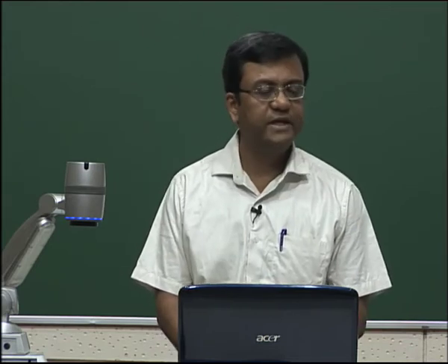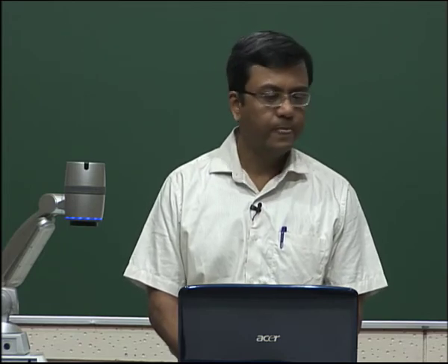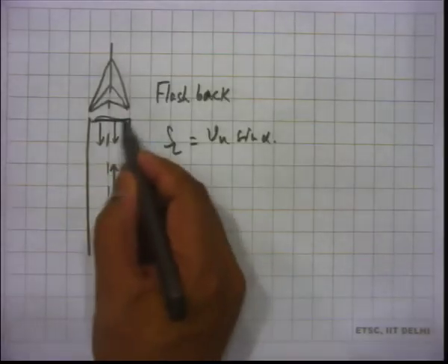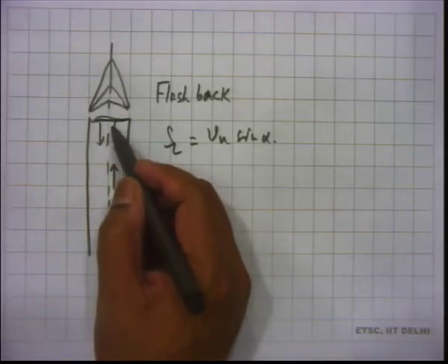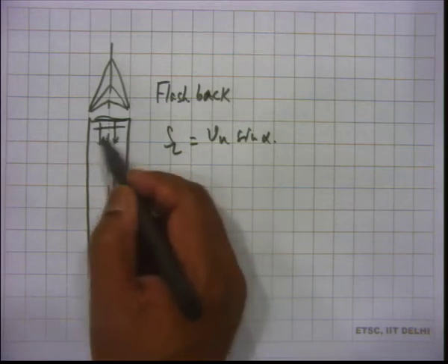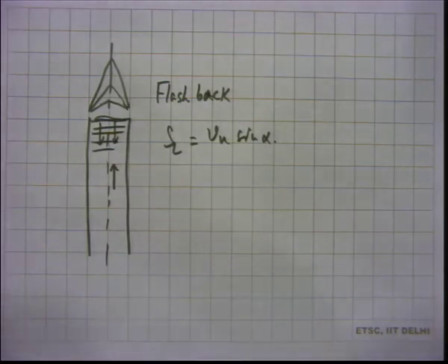If you reduce the feed, then the flame has no other option but to travel back in order to survive. So, the flame will travel back, and it tries to heat the mixture ahead of it, and if it heats it and ignites it, then you get the flame here, that keeps moving. Then it becomes similar to what we had been discussing some time back, that of a flame traveling in a tube, isn't it? We discussed how flame propagates.